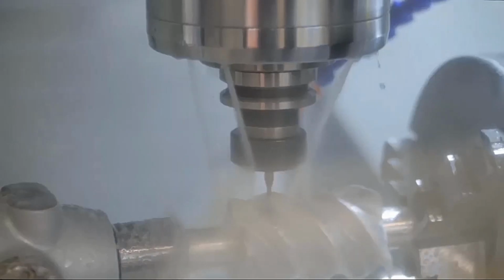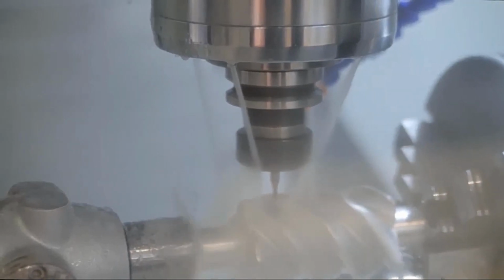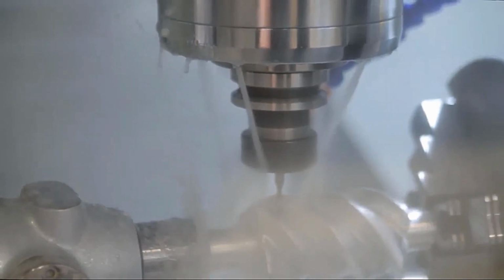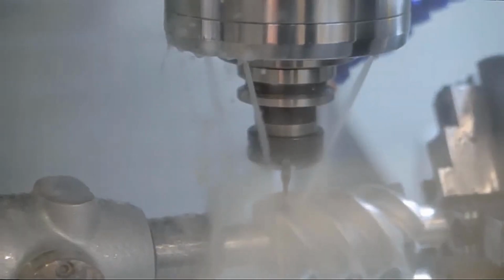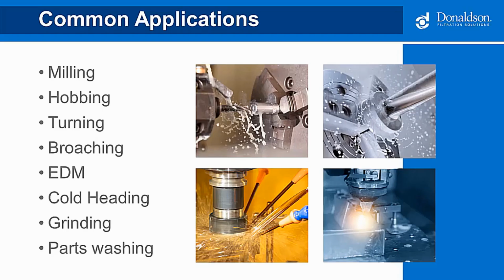We all know that machining is a subtractive process used to remove or chip away metal to create parts for other machines, tools, the transportation industry, and more. Wet machining brings oil or cutting fluid into the process for chip clearing, lubrication, and cooling. That's what you're seeing in the video here. Wet machining represents about 80% of the total market. The most common wet machining applications include milling, hobbing, turning, broaching, electrical discharge machining, cold heading, polishing, and parts washing.